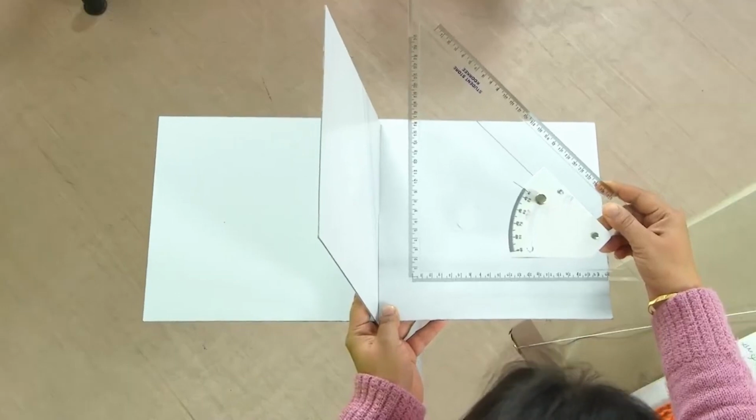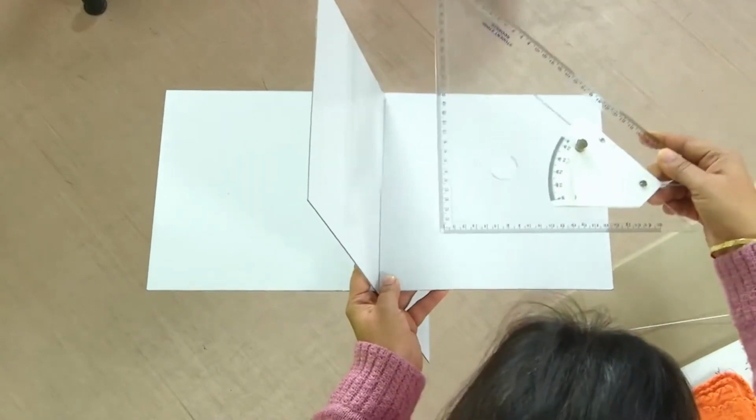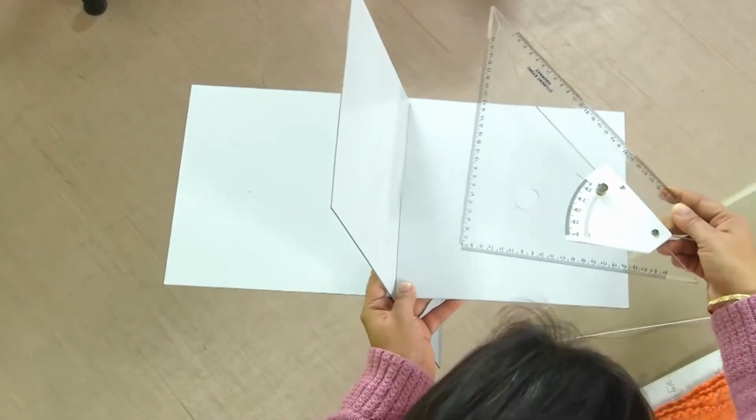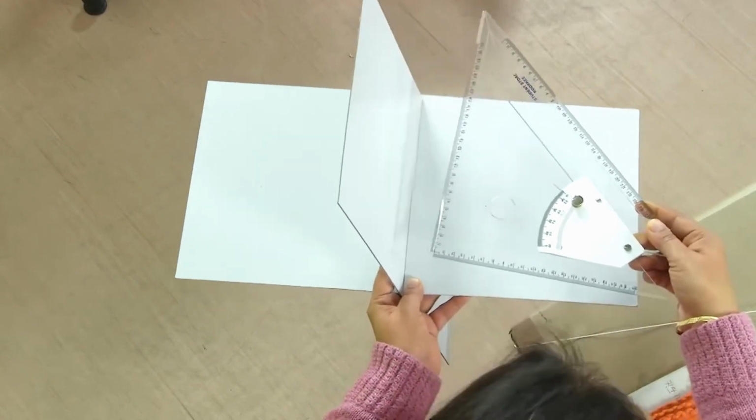So it is still perpendicular to VP and it makes an angle with HP. What do we see? We see that the line which we got as a projection on VP, which is the vertical trace, is now inclined but it remains the same length, and the horizontal trace is not the true shape anymore because it is not parallel to HP anymore. So we will have a diminished, slightly reduced size which will be seen in the HP.